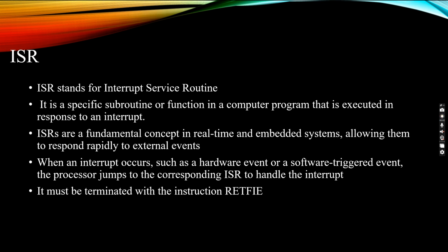ISR. ISR stands for Interrupt Service Routine. It is a specific subroutine or function in a computer program that is executed in response to an interrupt. ISRs are a fundamental concept in real-time and embedded systems, allowing them to respond rapidly to external events. When an interrupt occurs, such as a hardware event or a software-triggered event, the processor jumps to a corresponding ISR to handle the interrupt. It must be terminated with the instruction RETFIE. It stands for Return from Interrupt. It is an instruction used in code.